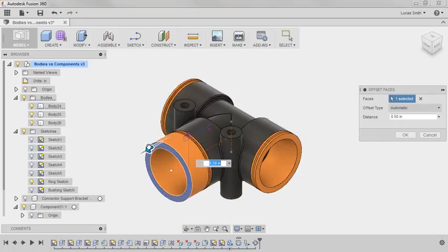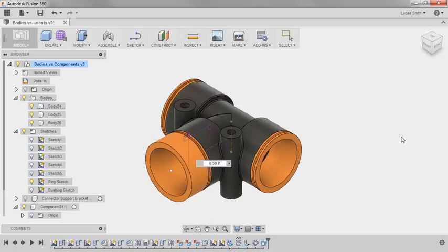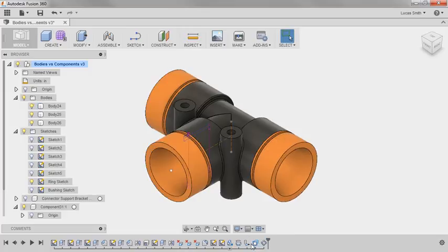This is because Fusion 360 treats individual bodies separately within the top-level design. However, because Fusion 360 is parametric, moving this modification in the timeline before the circular pattern command will cause all of the other instances to update as well. This is a quick and simple way to modify multiple bodies downstream. I'll quickly undo these changes to move on.